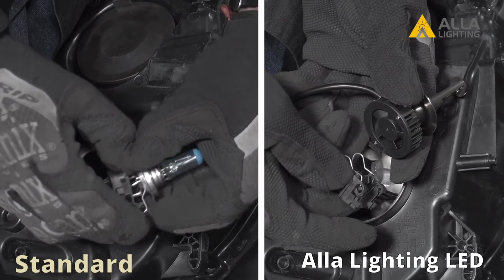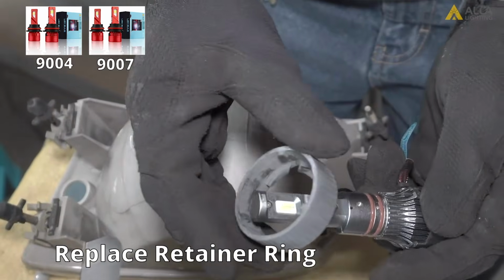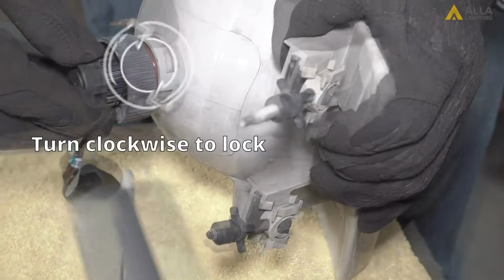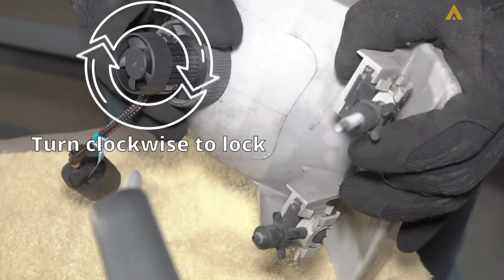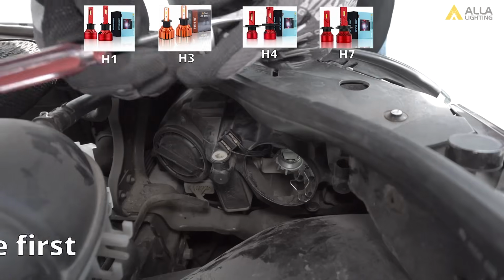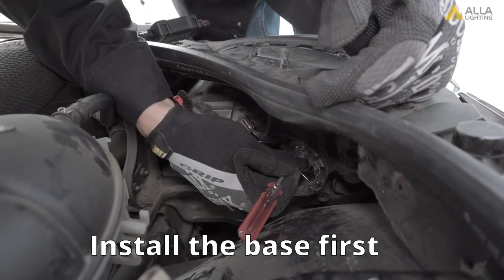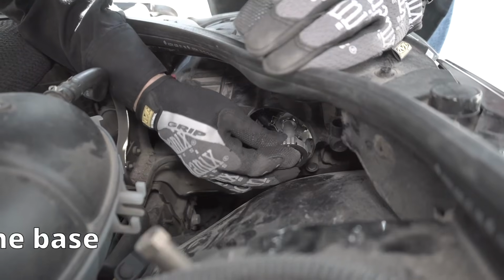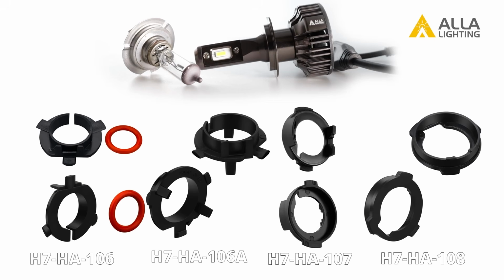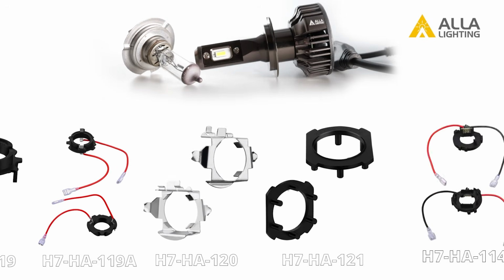Before you think you'll need an adapter, check these tips first. 9004 and 9007 LED headlight bulbs: the chuck from the LED bulbs can be removed and an OE adapter put in between the chuck and the fan. H1, H3, H4, and H7 LED headlight bulbs: the chuck from the LED bulbs can be removed and hooked to the headlight housing first. Then insert the LED headlight bulb into the chuck. If you find you need an adapter for LED headlight bulbs, compare the LED type adapter with the stock to make sure you'll get the correct one.